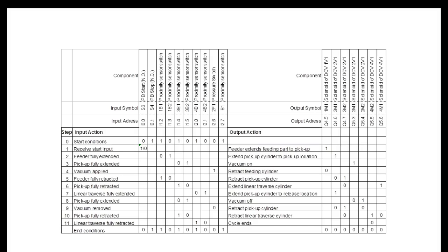We'll get some overtime. This is a new chart. I really like this one. This is the actual PLCs. So this gives us a really good indication of what outputs and inputs are supposed to be true to start something. So right off the bat, if it won't start, if I had this chart, I could go down through this list and see what's required to cause it to start. Well, all these right here are required to start. So right in here, I know input 0 has to be a what? 0, 1, 1, 0, 1, and I really like this chart. We can do any one of those.